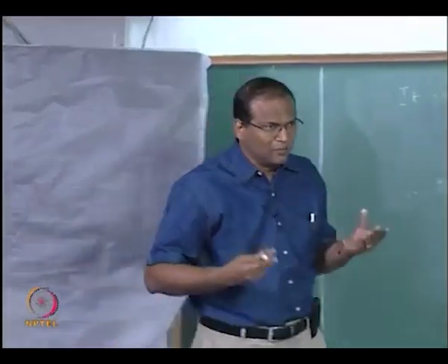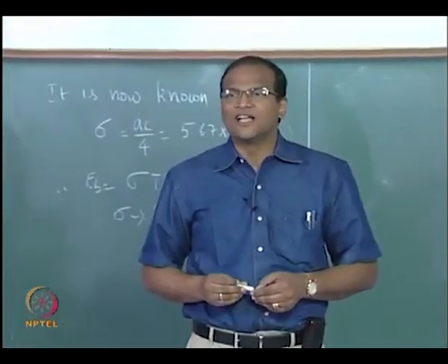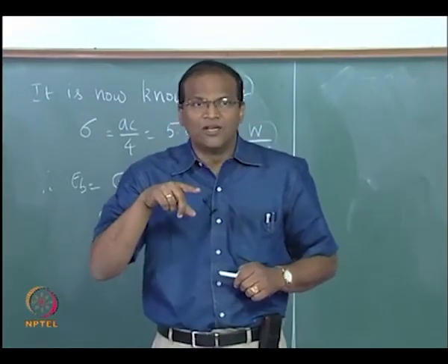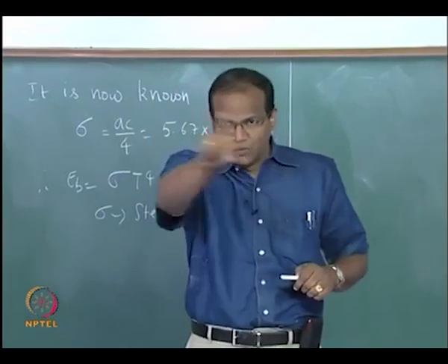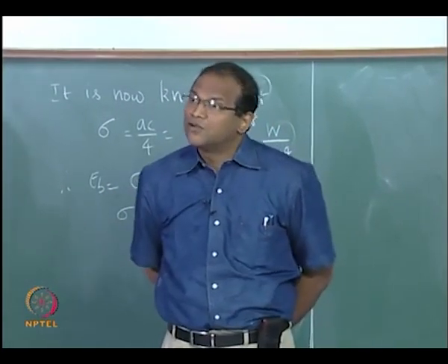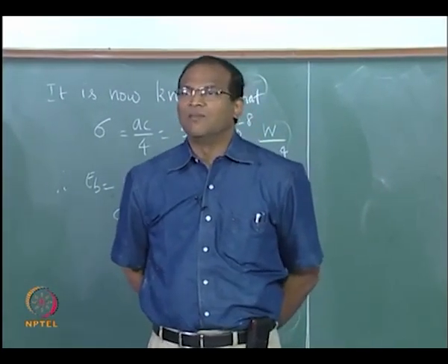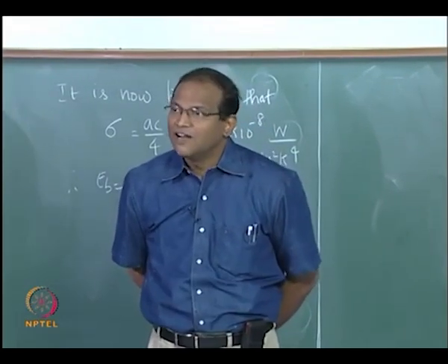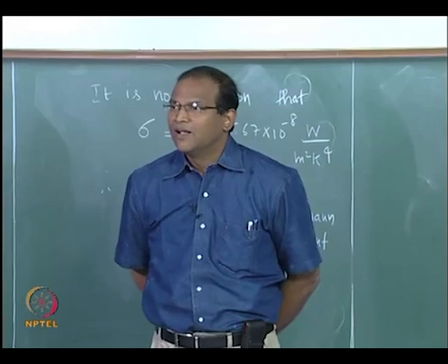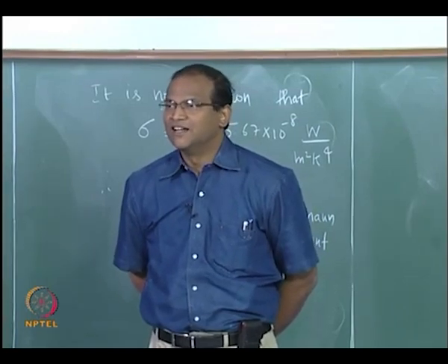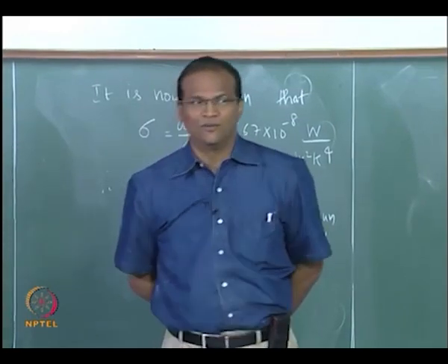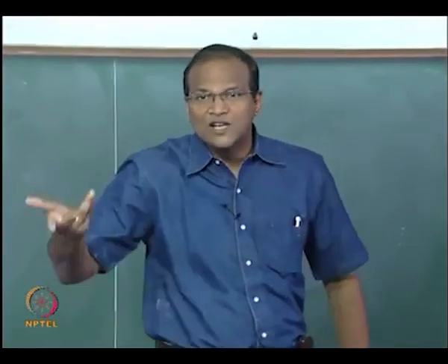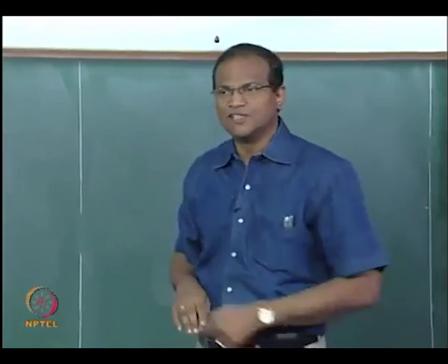Are you getting the point? Therefore, people started working out this candidate blackbody distribution. But please remember that any candidate blackbody distribution should also satisfy the integral over lambda from 0 to infinity, theta from 0 to pi by 2, phi from 0 to 2 pi, of I_B lambda cos theta sin theta d theta d phi d lambda, equal to sigma T to the power of 4. So it is actually an inverse problem. What is that I_B lambda which will satisfy all this?